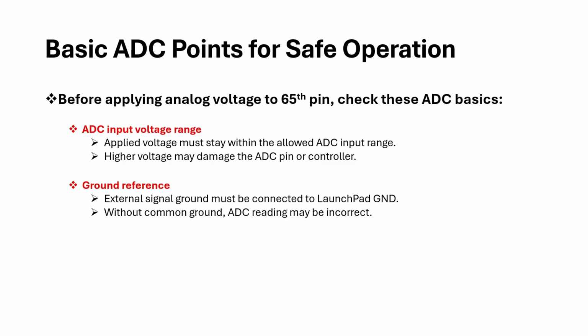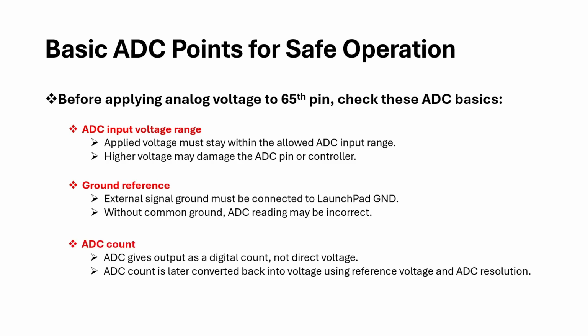The third point is ADC count. The ADC does not directly give voltage. It gives a digital count. Later, we convert this ADC count back into voltage using the ADC reference voltage and ADC resolution.